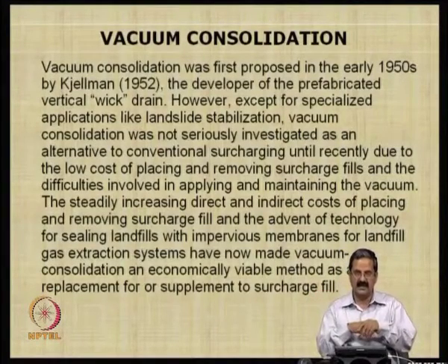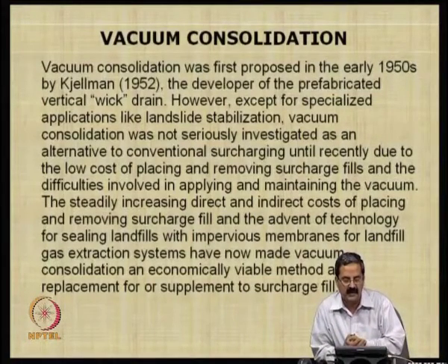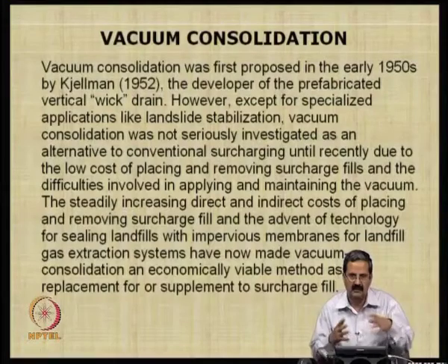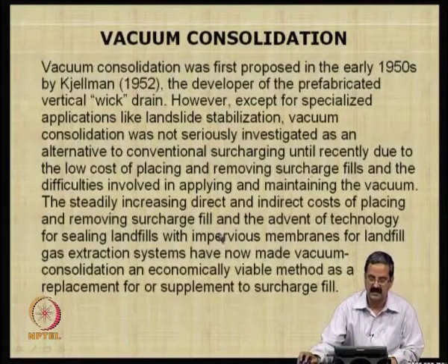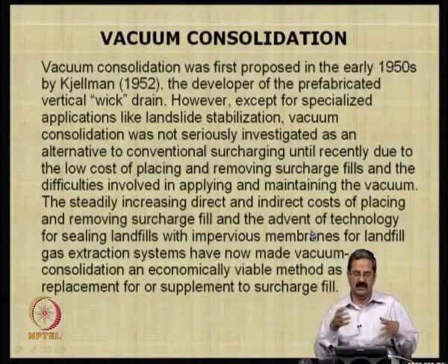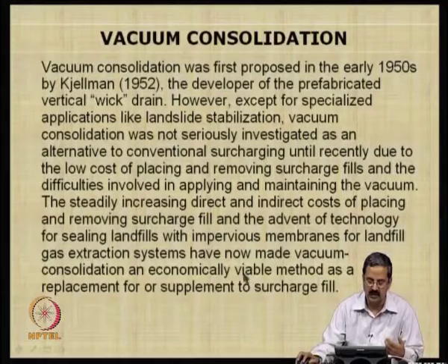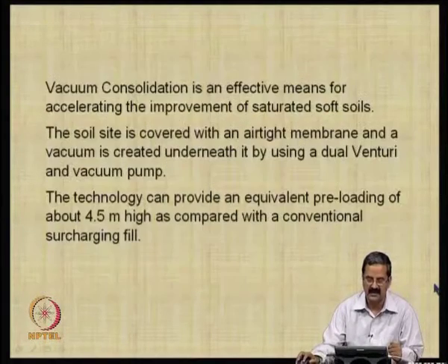The cost of the fill that you have to place for surcharge was also very expensive. So people use geomembranes in landfills, and you create some vacuum, using some vacuum technology for sealing. You can see the advent of technology for sealing landfills with impervious membranes for landfill gas extraction systems. The technology has improved so much that it has become more economical and viable as a replacement or supplement for surcharge fill.